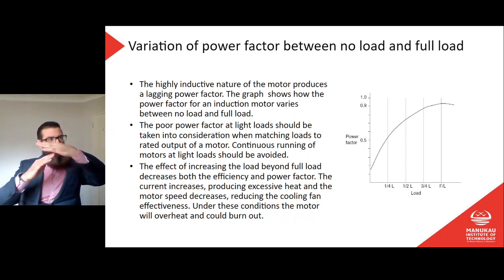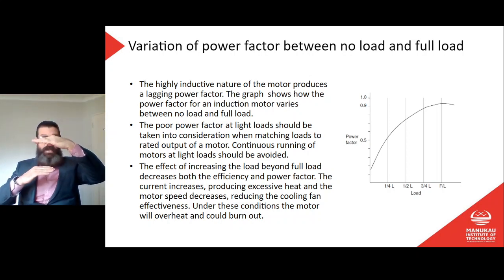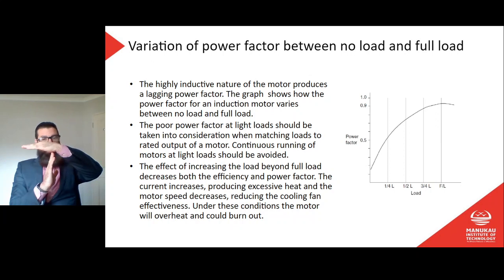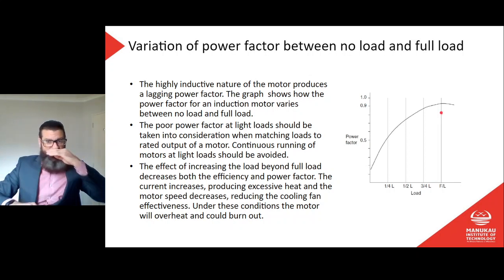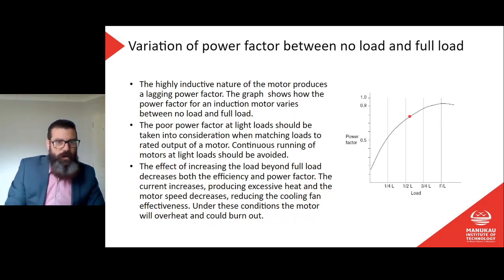Remember, our power factor is another way of representing the angle of lag. So if the flat line on our graph is our resistive power, then the angle of lag, so 90 degrees or a power factor of low, like 0.1 or something, would be there. And then as we increase our power factor, our angle of lag comes closer and closer to that horizontal, which would be 1.